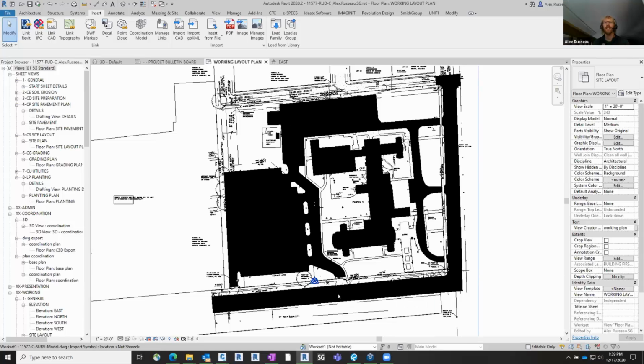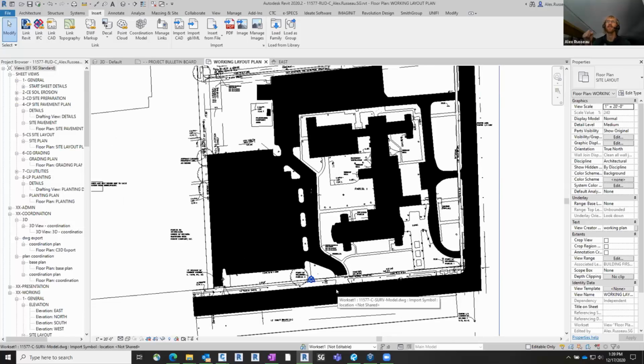Yeah, worst case scenario, building corner, but not all buildings last, especially if it's an old one. Those could get moved. And oftentimes if you've got a survey stake, trying to go up against a building, you're never going to get exactly there because the width of the rod that you're using is always going to be in effect. So benchmarks are the best that you can use.